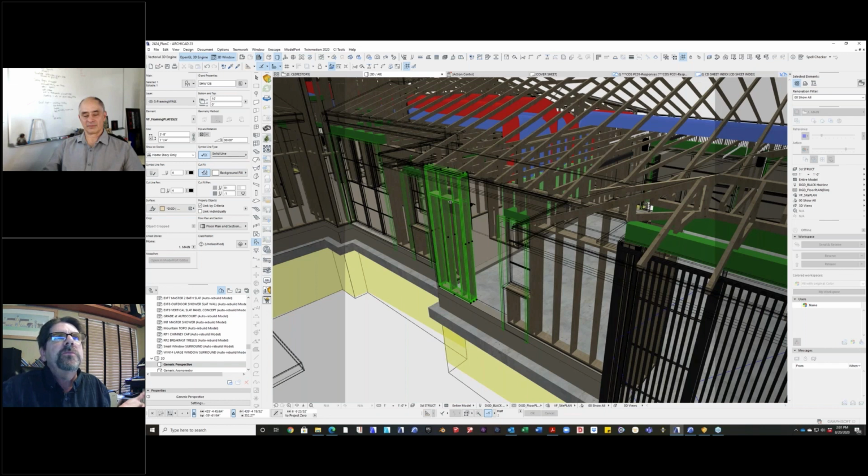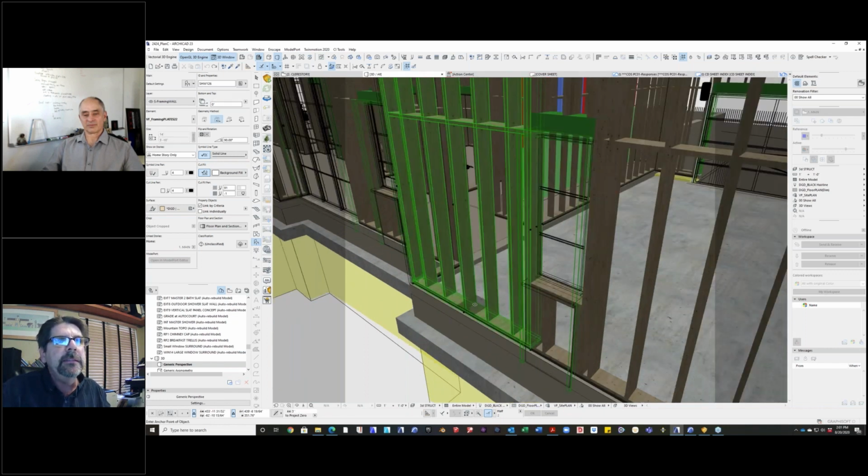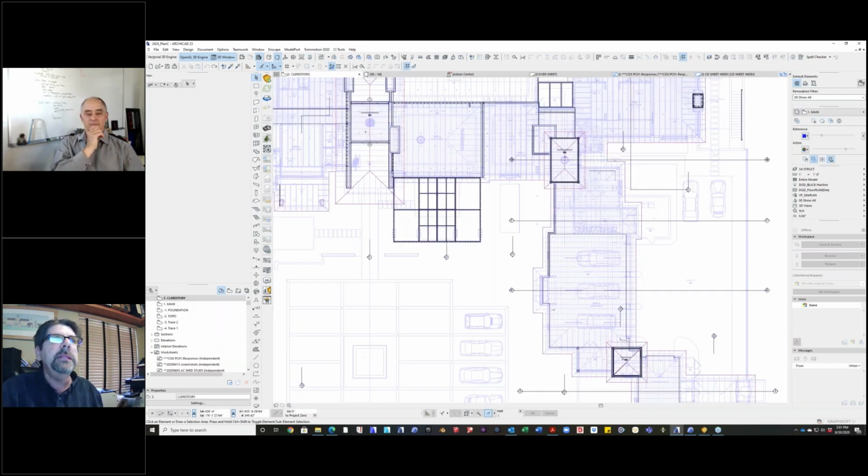All the plan checkers wanted to see where the blocking was, so I got 2 lines of blocking that you can add into this. And then, everything is, the width of this wall, I can just stretch the width, same way as the height. So I can match whatever I've got going on in plan.